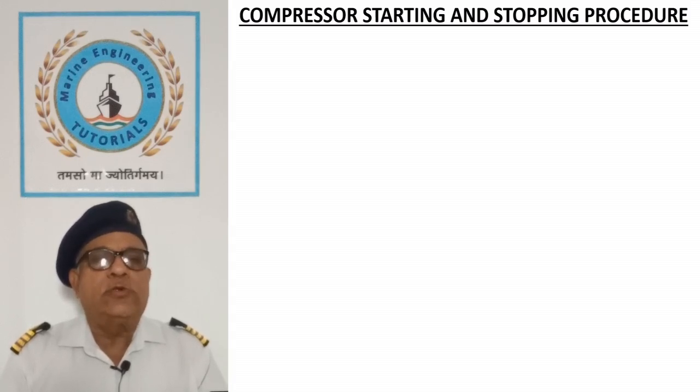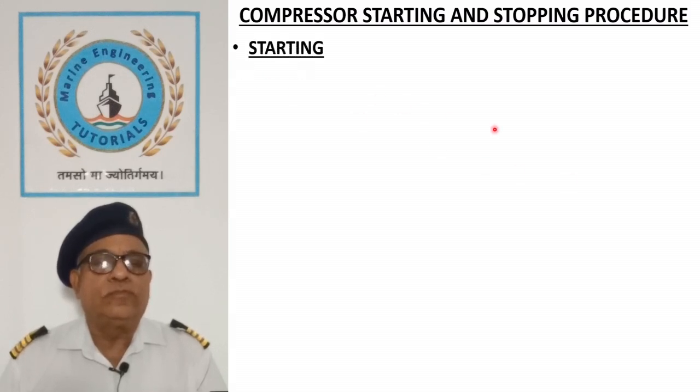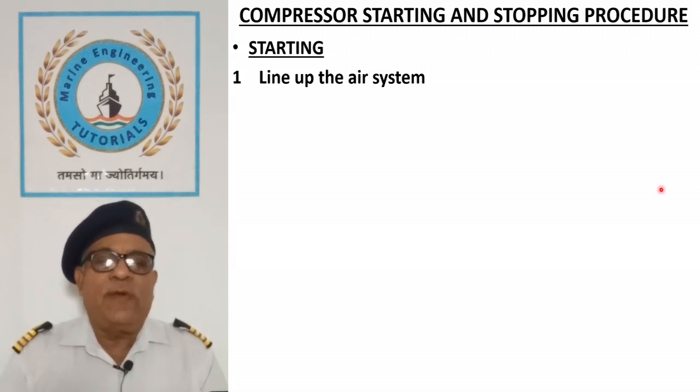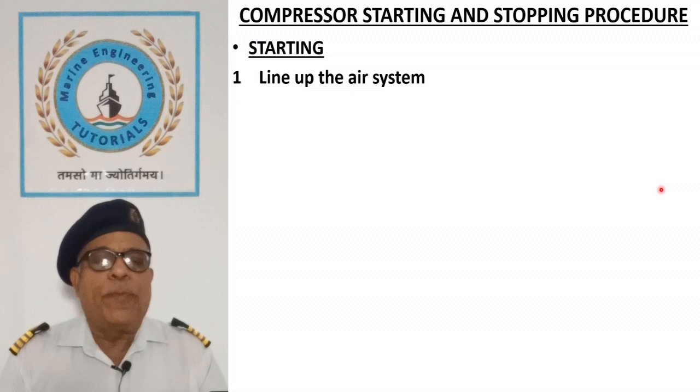Compressor starting and stopping procedure. Air compressors are started in the unloaded condition. Compressor operation is usually automatic, although the following procedure is adopted for manual operation. Starting. Line up the air system. Confirm that compressor outlet and receiver filling valves are open.